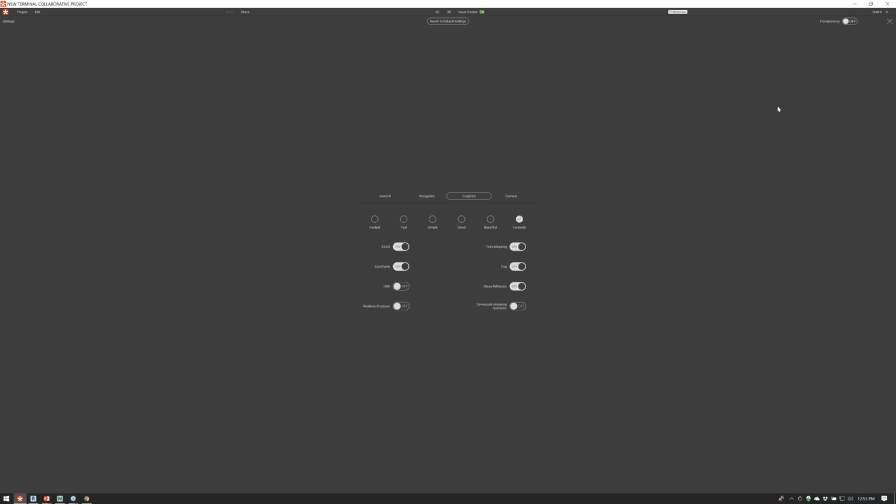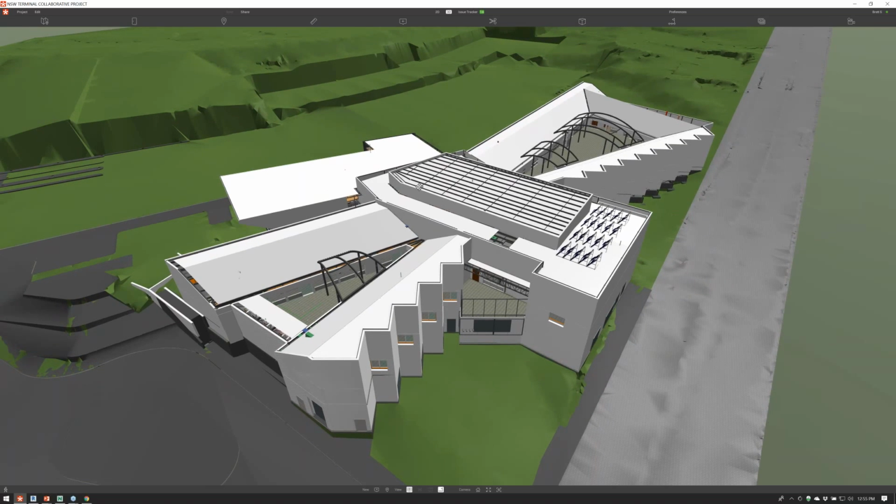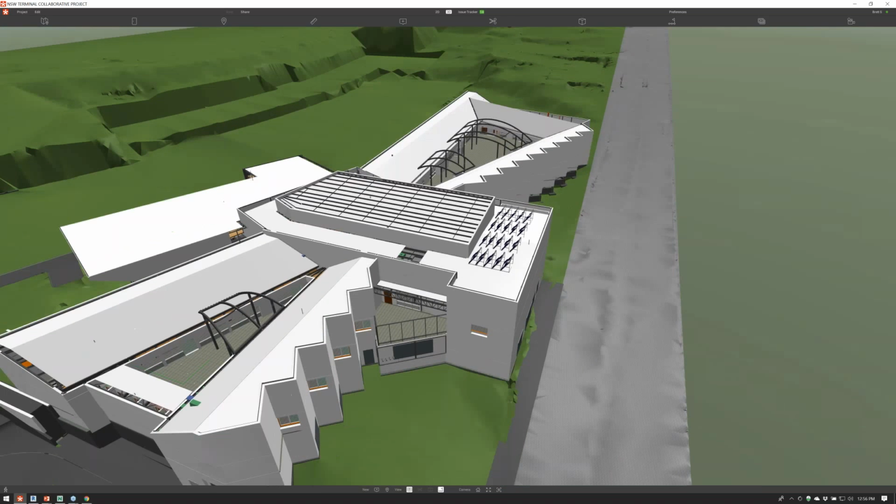But we have clients that are as far back as 880s, in the 8 series of NVIDIA cards, and they're not having a huge problem either. I would say that if you can run it in Navisworks, it should actually perform slightly better in Revizto, if not a lot better. So think about that. When you start getting up into 1.5 gigs of Revit data, you might just see some dropouts. But I've worked with projects as big as 800 megs with 1,500 sheets in full graphical quality, and have not had many issues at all.